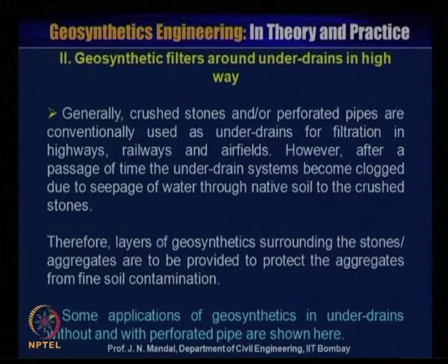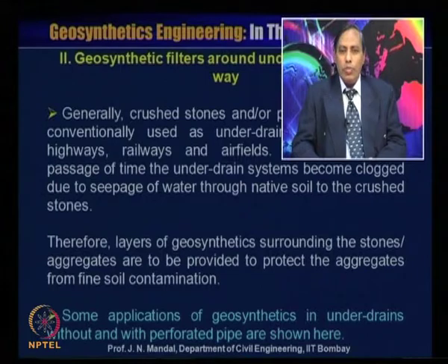Generally the crushed stone and perforated pipe are conveniently used as under drain for filtration in highway, railway and airfield. However, after a passage of time, the under drain system becomes clogged due to the seepage of water through native soil to the crushed stone. Therefore, a layer of geosynthetics surrounding the stone or aggregate is to be provided to protect the aggregate from soil contamination.